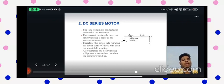In a DC series motor, the field winding is connected in series with the armature. The current I passing through the series winding is the same as the armature current. Therefore, the series field winding has fewer turns of thick wire than the shunt field winding. Also, the field winding will possess a lower resistance than the armature winding. You can refer to the circuit diagram given.